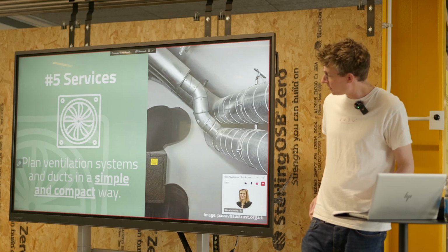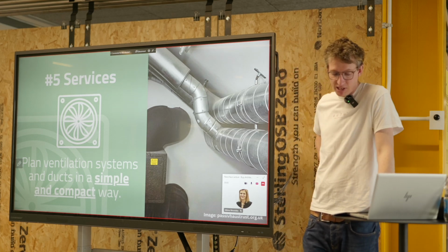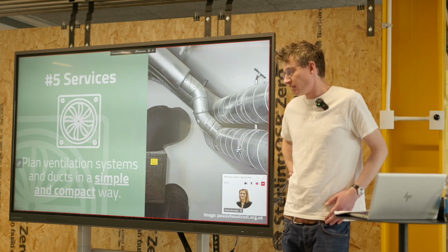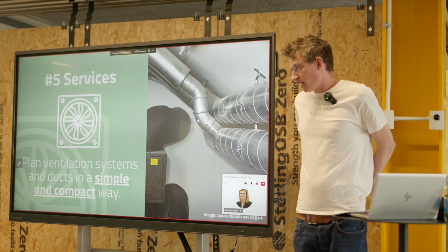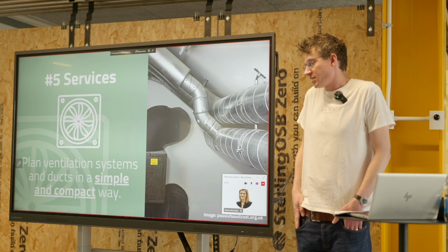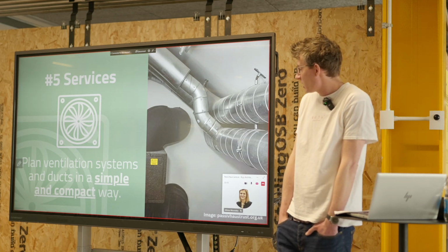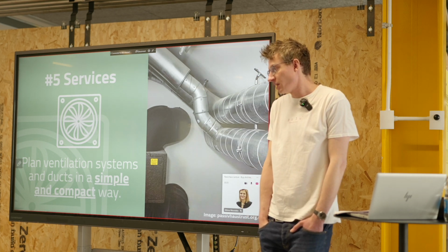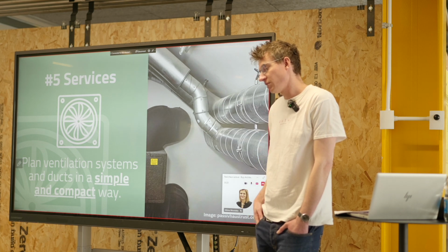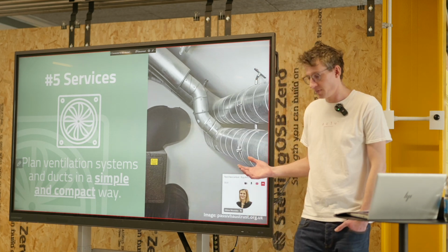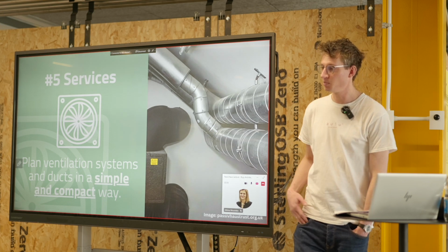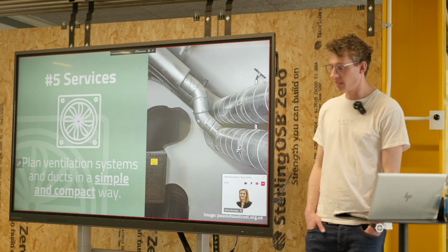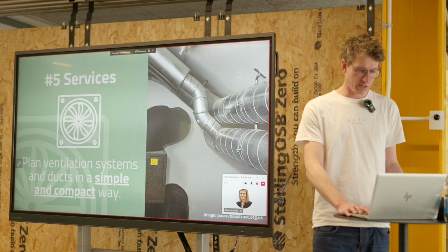When you're designing the services, it's also worth considering the heating strategy for the building. Space heating, hot water heating, and storage as well. From my experience and speaking to experienced passive house contractors and designers, they actually don't advocate the use of hot air for heating systems for passive houses. They'd recommend more traditional heating systems, like radiators or underfloor heating, as they're much more controllable, and they can also tie into things like air source heat pumps as well, which is an important part of renewable sustainability.